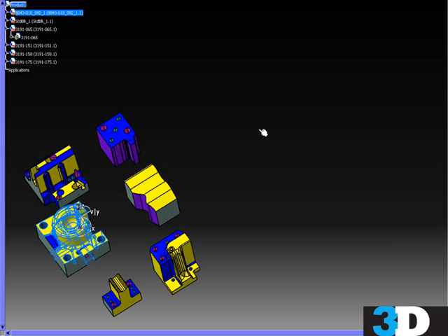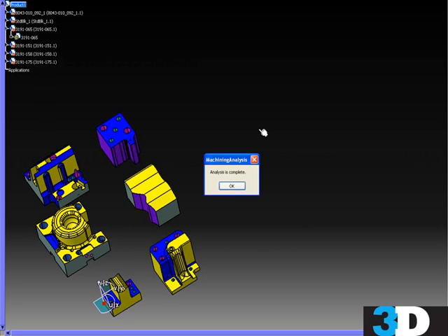And then it also allows you, if you see some of the block sizes are maybe non-nominal or not what your customer gave you as raw stock, maybe they ordered a block with an extra 1/2 inch on it or things like that, you can actually go in and manually edit the block sizes that it analyzed, and it will recalculate the rough cutting that has to be done to remove that extra material. It does it all quick.